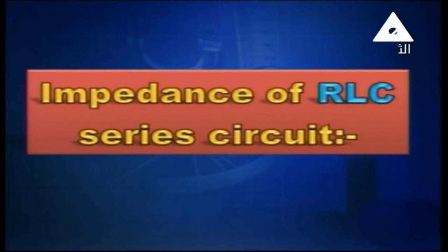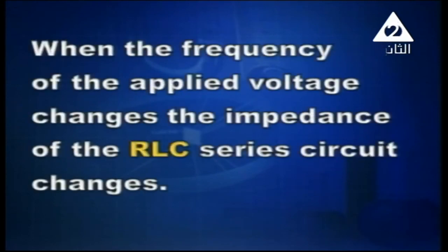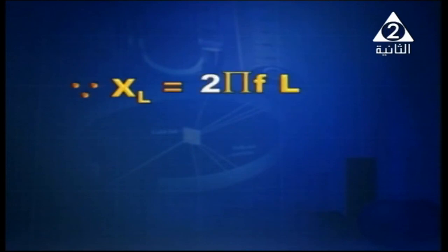Impedance of the RLC series circuit. When the frequency of the applied voltage changes, the impedance of the RLC series circuit changes. XL is equal to 2 pi F L. Since XL is equal to 2 pi F L, the relation between XL and frequency is direct.